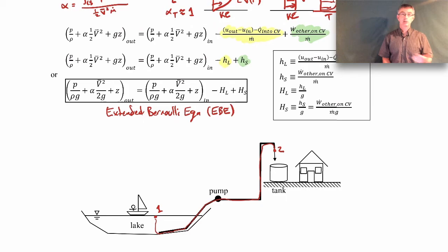The way I can check whether it's laminar or turbulent is I just calculate the Reynolds number. If the Reynolds number is less than 2300, it'll be laminar. If it's more than 2300, it'll be turbulent. That number of 2300 comes from our Navier-Stokes equation analysis of Poiseuille flow, or viscous laminar flow through a pipe. We'll come back to that in a different lecture as well. So this is the energy coming in, this is the energy going out. But of the energy coming in, some of it is lost due to viscous losses.